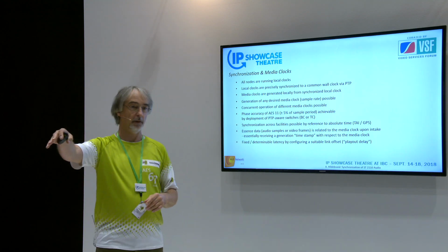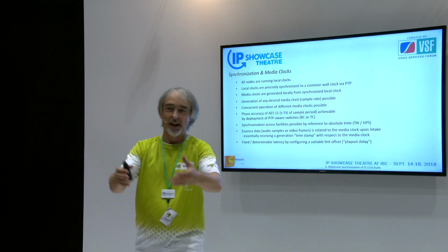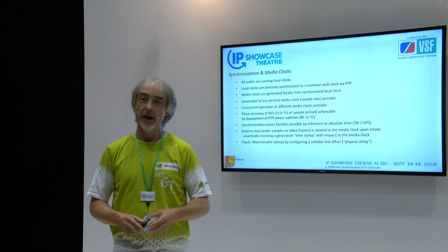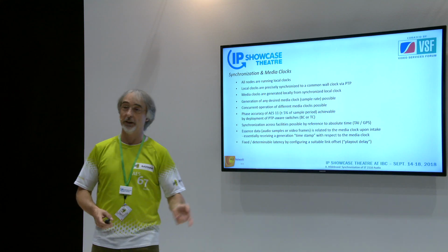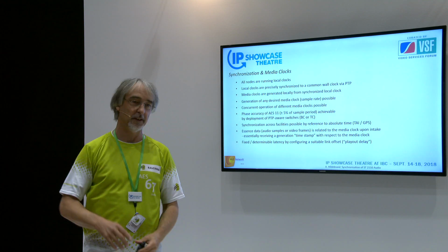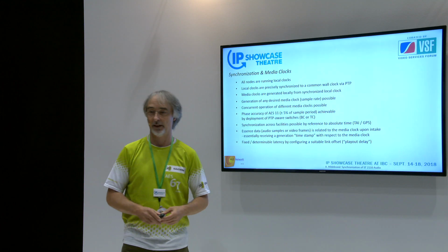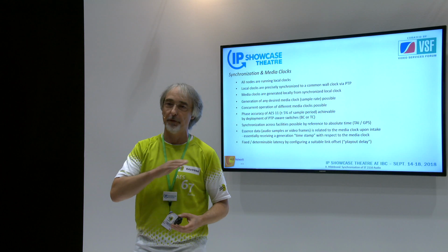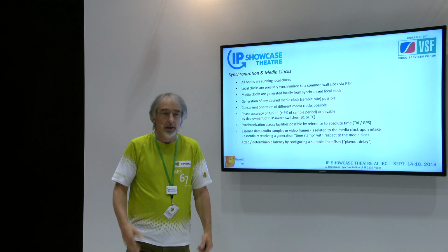Now, front of house needs the very same content. Do we have to create another stream just because that has a different processing delay? It doesn't have to have 2 milliseconds. It can work with a 5 millisecond processing delay because there are other streams coming from the stage or elsewhere which need to be correlated maybe. No, it can receive the very same stream because it knows when it's created. We can still work with a 5 millisecond processing delay in order to be able to arrange it with other streams. And then there's the OB van outside. He also wants to have that direct stream. He can receive the very same stream. It knows when it's generated, but he said, okay, I have a relaxed processing requirement.